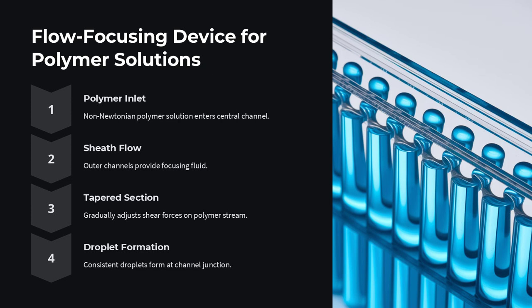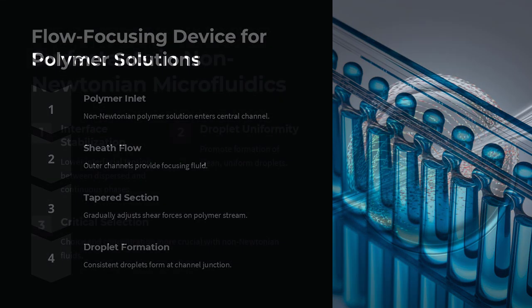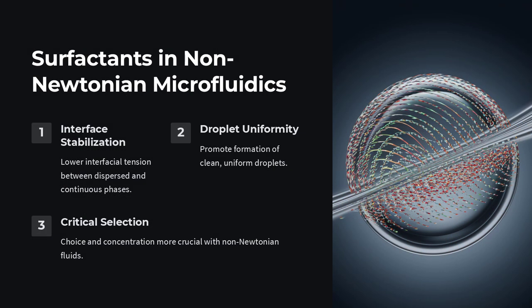During droplet generation, the stretching of these polymer chains under shear can result in delayed breakup, leading to larger or irregularly shaped droplets. Conversely, if the viscoelastic effects are balanced properly, they can enhance the formation of a well-defined droplet interface, which solidifies into a stable capsule wall once the droplet is cured or cross-linked.